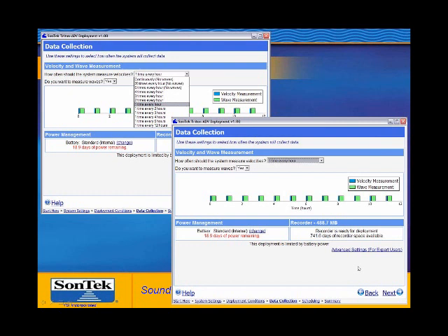That's actually a good point, because one thing I wanted to make clear is that the Triton will not output the wave data in real time. The wave data is actually processed post-deployment through our software. So the Triton can deliver the current data, the velocity data, in real time, but not the wave data, the PUV. But post-deployment, you can have all of the raw data from the PUV, should you like to use any external programs to process it on your own.